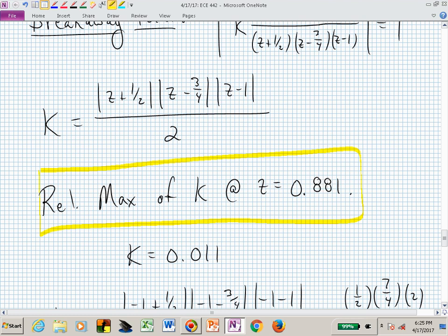So it is trial and error, but it's a guided trial and error because you know that you're searching for this bump. It starts at 0 at 3/4 and 1, and you're just continuing to increase, and you're looking to find where I reach that relative maximum. That's my z value that is the breakaway point. Yes, so the question was, if I graphed this, you could now find the relative max of that graph, and that value of z where you reach that relative max should be your breakaway point. And your calculators can do that for you if you want. Some of them can.